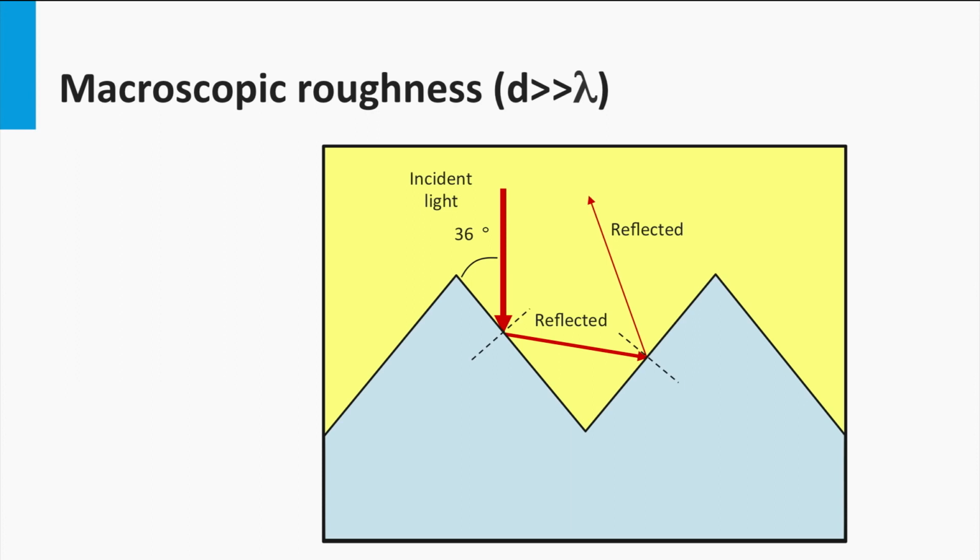As discussed last week, texturing of the surface can improve the light incoupling as well. Light that is reflected at the textured surface can be reflected at angles in which the trajectory of the light ray is incident somewhere else on the surface. Here the light can still be coupled into the silicon. Secondly, the scattering at textured surfaces will couple the light at angles into the wafer. This means that the absorption path length will be enhanced. This certainly enhances the absorption of light with a wavelength above 900 nanometers.